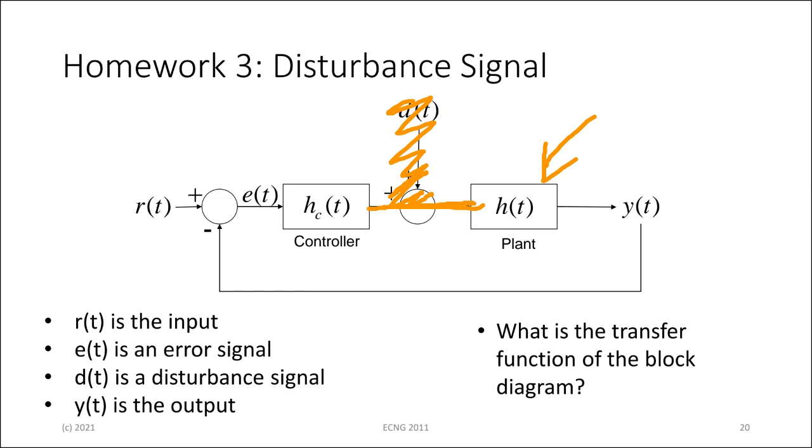And the plant does something, and then you have a controller block. Now the controller block is where the inputs from the user come in. So the user sets certain things, like if you're making methanol, for argument's sake, it will set the flow rate for natural gas. It will set the temperatures for the pressure chambers. It will set the flow rates for liquids coming in and out of the mixing vessels and the like. Pump speeds, therefore, to cope with that, valves to open and close and shut and the like.